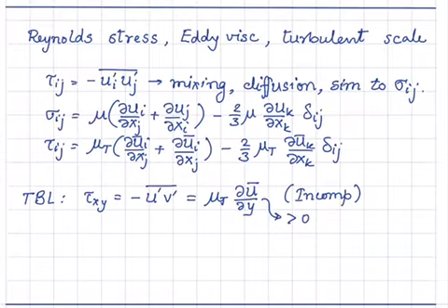In a turbulent flow, when we measure u prime v prime and calculate the average of this product, it turns out that this quantity is negative. There is a physical interpretation for this. We will not go into it at this point. It's a bit advanced. But if you measure it, and people have reported in many different experiments on turbulent boundary layers, they have found it to be negative.